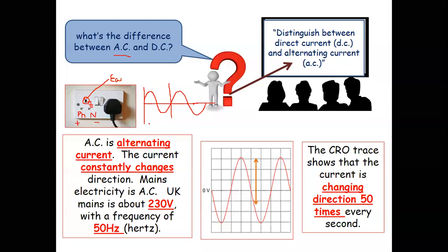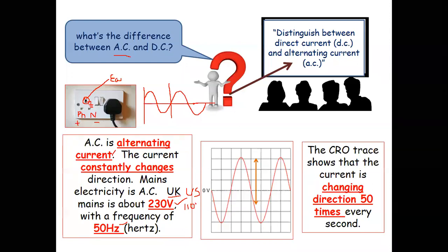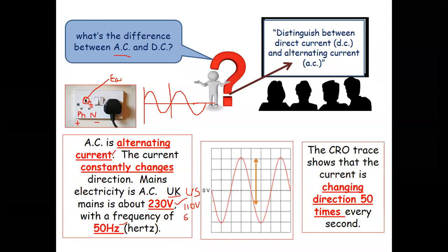So when you give an alternating voltage to any equipment, the current drawn by the equipment is an alternating current. So alternating current will continuously change its magnitude as well as direction. Generally in UK or India, the voltage which we are going to get is 230 volts with 50 hertz supply. If you went to the US for your studies, in the US you will not get 230 volts or 220 volts. We are going to get 110 volts AC supply with 60 hertz.